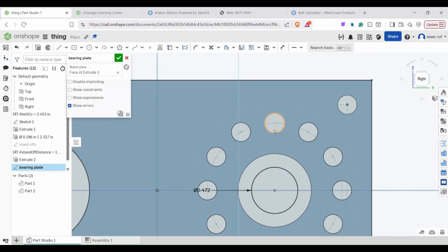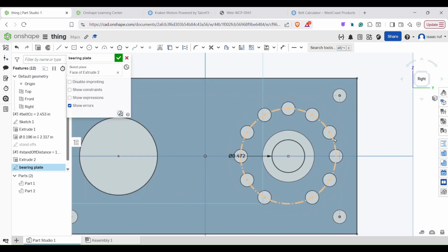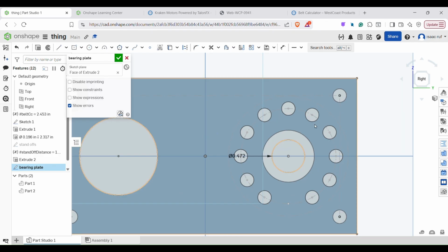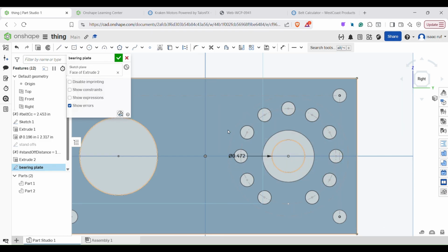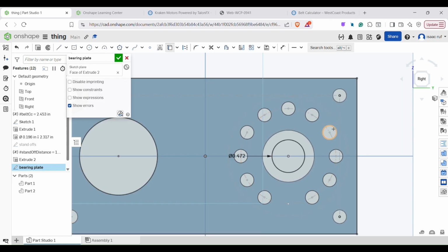I also want to use all of these circles here because you'll notice we want to be able to put these screws in, but once we mount the second plate on there, they won't be accessible. So you need to make sure that you have clearance for the bolt holes. So we'll use all of these too. I can actually just make a little box around them, oops, that didn't work. Never mind, that won't work. I'm going to use all these little circles, and that just makes it so. And you'll notice I'm not using the points; I'm using the circles because when we update our hole size there, that hole we made, it will automatically update these holes. And these are just clearance for the holes. They can be the same size as the bolt clearance, but yep.